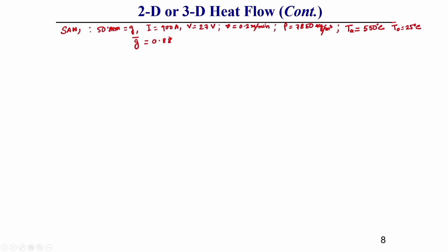You can calculate this thing. So, which is generally less than 0.9. So, as it is less than 0.9, directly it is a phenomenon of 2 dimensional types of heat flow. That means, here the heat flow is parallel to the surface of the plate, there is not 3 dimensional types of heat flow equation. So, in this case you should use what types of heat flow equation, that is 2 dimensional types of heat flow equation I have already derived, that is generally based on line heat source, whatever the equation you got, that equation you should use in this case.